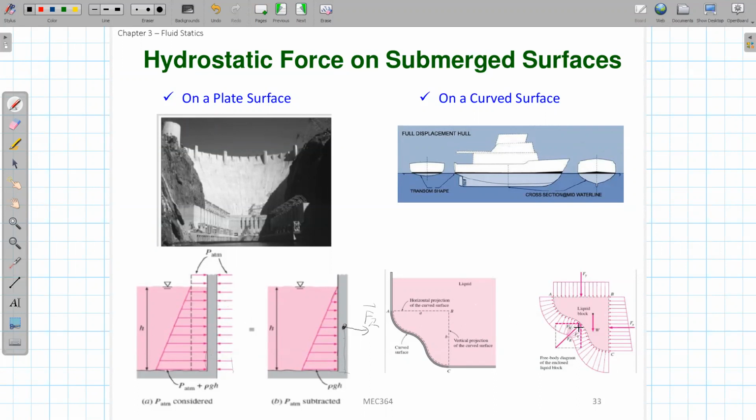And in these cases, maybe we can also try to reduce all these pressure forces into a single resultant pressure force, with some location and also some direction. If we can find that, we can make our design of this boat very simple, because we just make sure that the boat body is strong enough to hold this single force at some location. Okay, so this is our task.